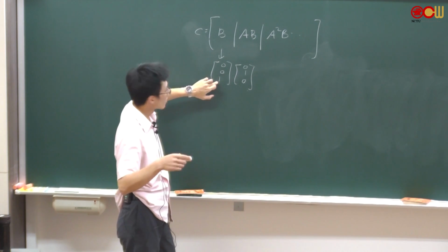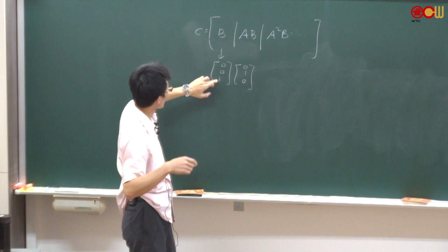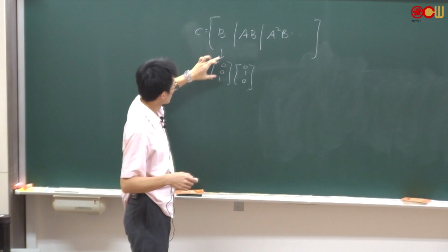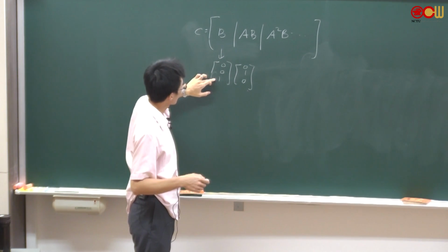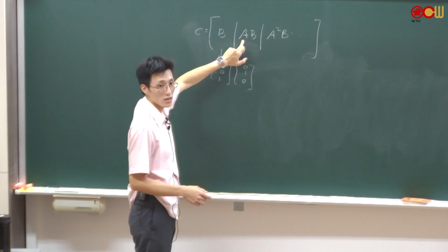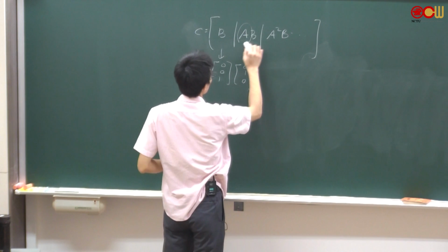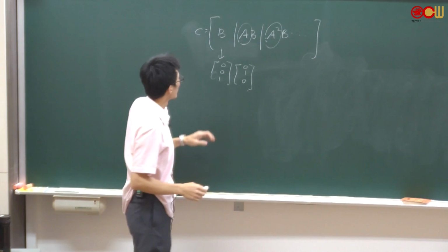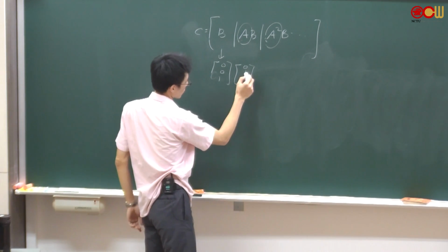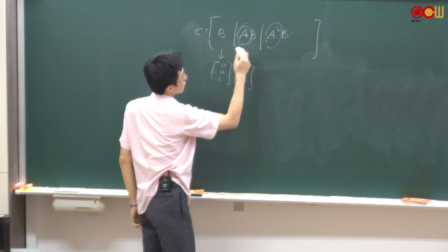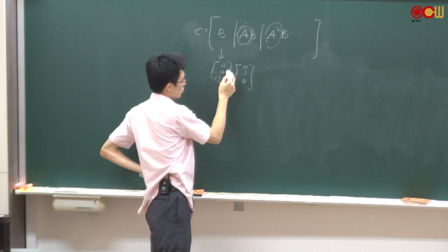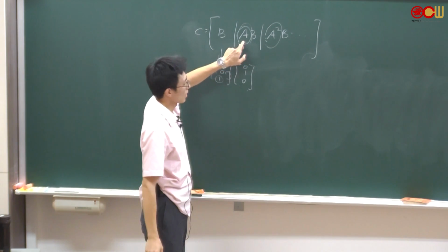But at the next time step, I evaluate A times B because the change of the third element can affect another elements 1 or 2, depending on what A is. So it's kind of propagate in time that how this control input can affect another element. If it's 0, 1, 0, that means the contribution of A in this product is that element can change the second element based on the natural dynamics of A.